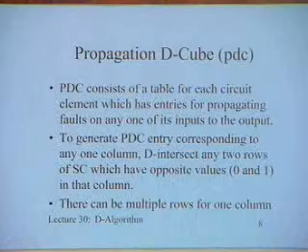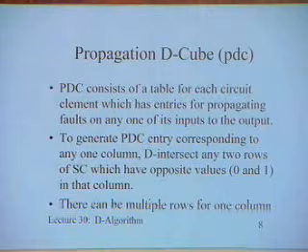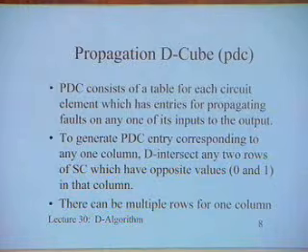D signifies that that particular circuit node has a different value under the fault condition and a different value under the true condition. The whole algorithm is based on trying to push this node D to the output, so that at the output I can see the output becomes sensitive to that fault. Basically, even in Boolean difference we did the same. We want to make the output sensitive to a fault, and the output is sensitive to a fault if it behaves differently under the true and the faulty condition.